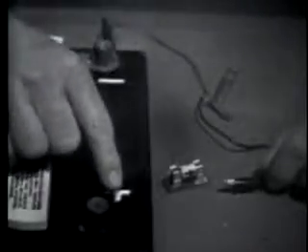The bulb lights, so there must be current through it. Now I'll turn the diode around so that the arrow is against this flow. Remember, if current flows from negative to positive, the arrow is against that, so it should block it. Let's see. Making the connection, the bulb doesn't light. So just as the control valve blocked the flow of water, this diode is blocking current.